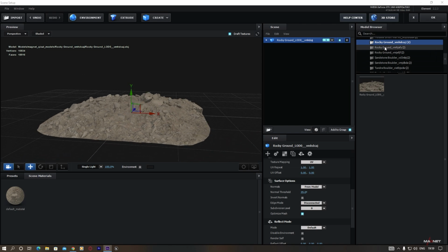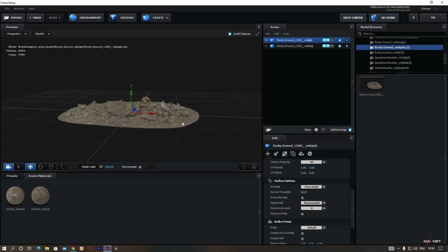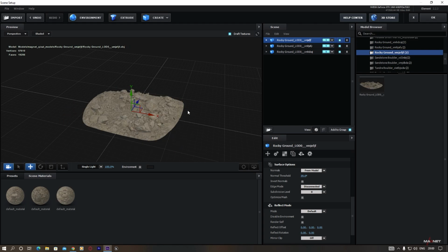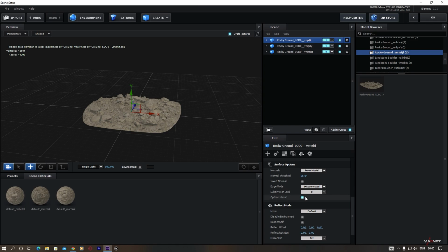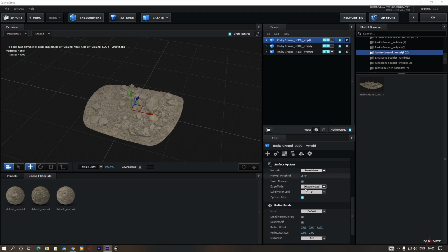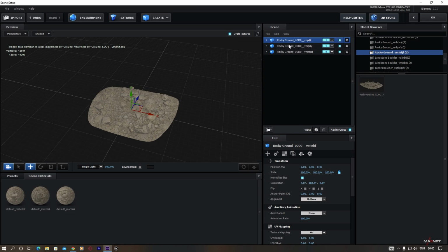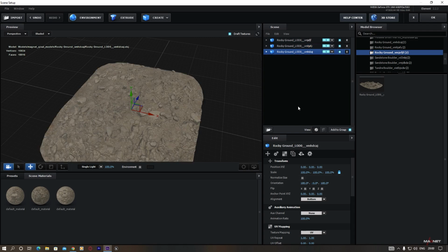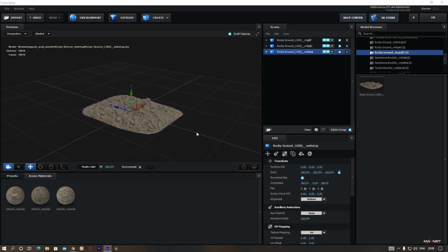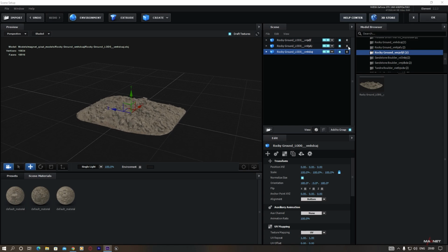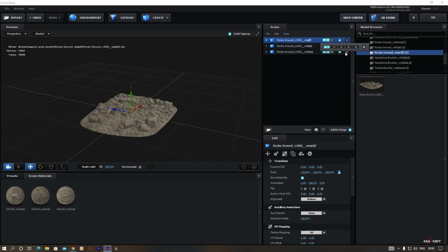Okay, and then we use another ground model here, so just click here. Make sure that you choose this optimize mesh option here as well, and also do the same for this third one. Just click and it will import here, and click on optimize mesh. Okay, and we also do one thing: go to the normalize size option here, just click here, and do the same for this one as well, and also this. In this way the sizes of all these models are identical, and we also put all the models in group number 5, so make sure of that. Okay, and then we hit OK.